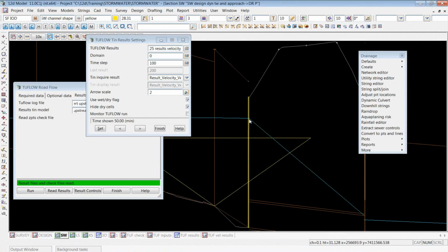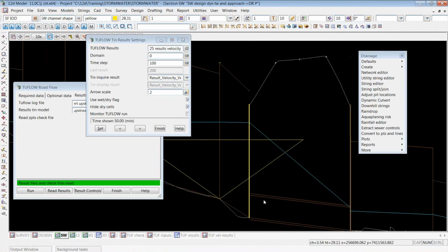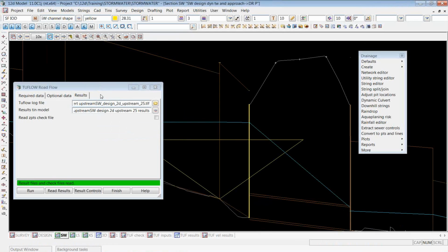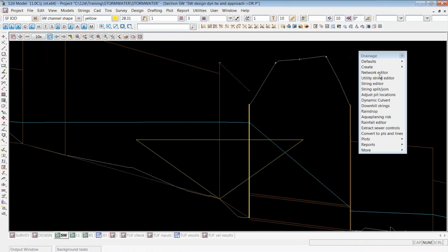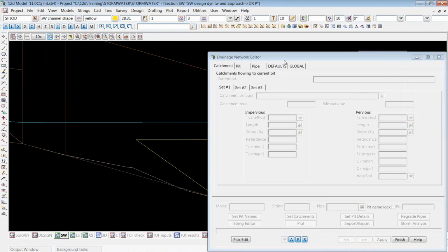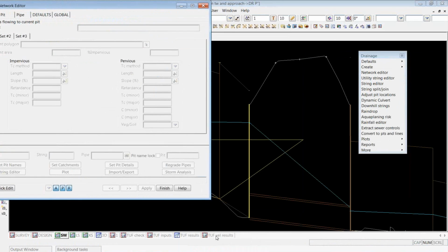What we do is when we present our reports, we will put the KU losses in our reports. Now, when we're talking about a culvert, there's 2 types of losses. There's, of course, the entrance loss and the exit loss. And those coefficients are constants, okay, when we're looking at culverts, and this is specifically about culverts. If we're looking at stormwater pits, that might be a completely different issue. But let's go grab my network editor just for a moment.